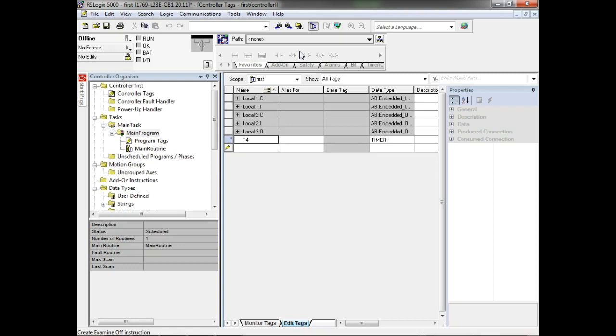With the Siemens PLC, you can run what we call an ID and it'll go out there and do it. Now, I think the 5000 will do that for you too. It's just I don't know how to do it. So once you've got communication with your PLC, you can go out there and say, hey, who are you and what do you have on you? And it'll automatically do this for you. So all it's giving us right now, but on the 1100, what we would have to do,